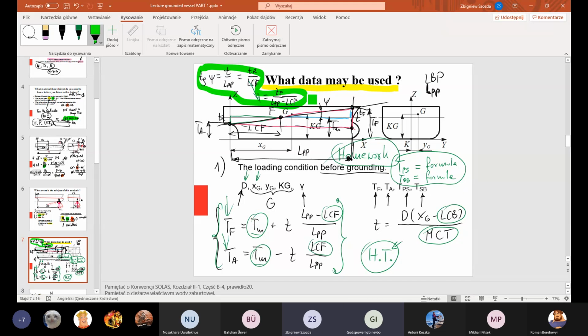No, it is not length overall. This is length between perpendiculars, so the transom at the aft is ignored here, and the bow is ignored. I can see, it's just between the perpendiculars and not the full length of the ship.